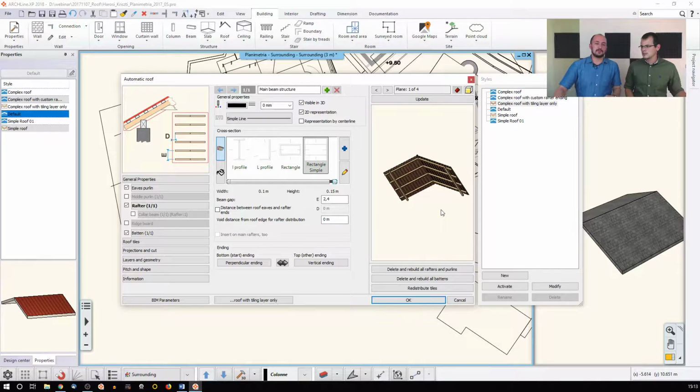And in many structures, you can see that there is a rafter frame which is kind of stronger than the others. So it has a different cross section. Sometimes the cross section itself is also different, but sometimes it's the same, just with bigger thickness and height. So you can add multi-framing to the same roof. You don't have to build one roof, two roofs, three roofs just for the same reason, but you can have multiple varying sizes of rafter.